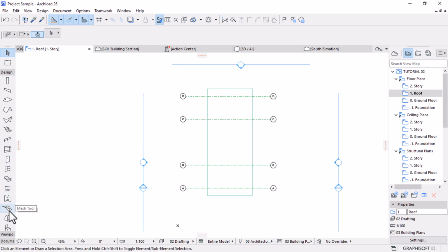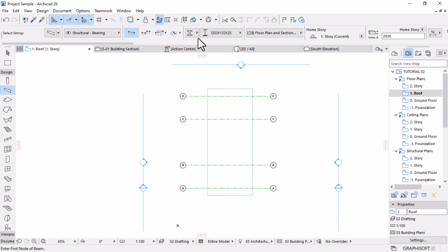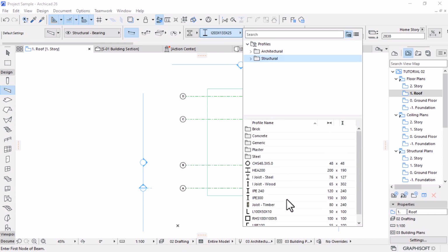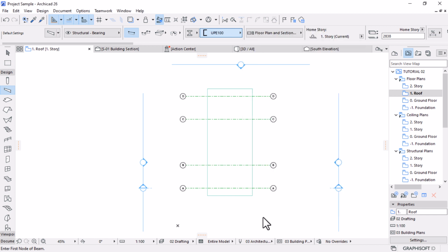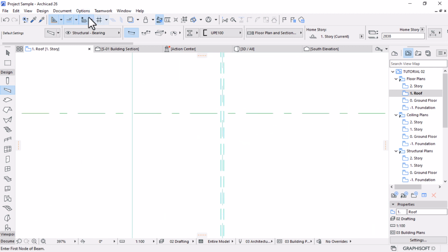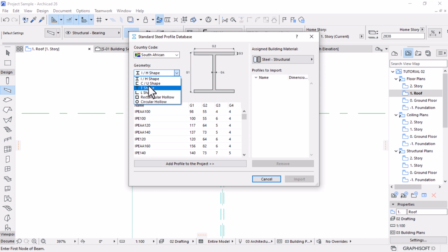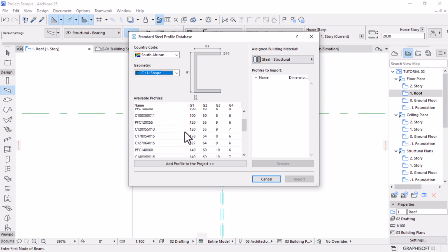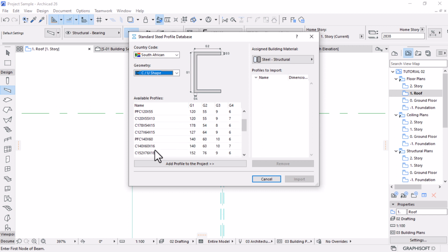And then what I'm going to do is use a beam as well, and this time around I'm going to use a U shape instead of this angle line. A U shape, and then let's just draw it there to there, but it looks small. I think let's go back to options, complex profile, and import a U shape. Still, let's find a U shape. We're going to use it as a gutter, and let's find a size that we can use for the gutter.